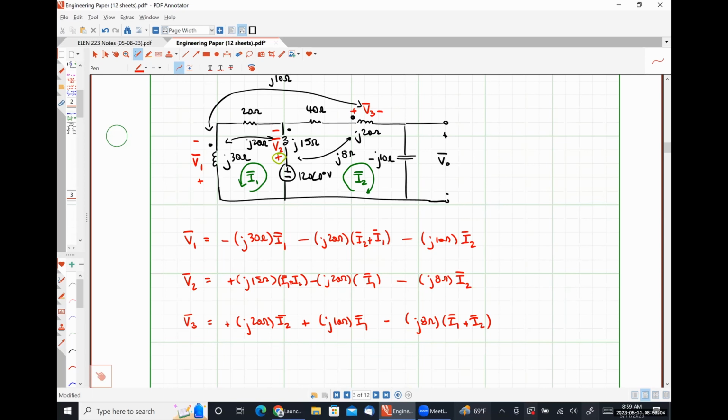So there are always two criteria that you need to look for: where the positive polarity terminal of the voltage is with respect to the dot for that particular inductor, and then the direction of the currents flowing into the dotted things. Probably the most confusing thing here is, let me see if I can spell this out as obviously as possible.